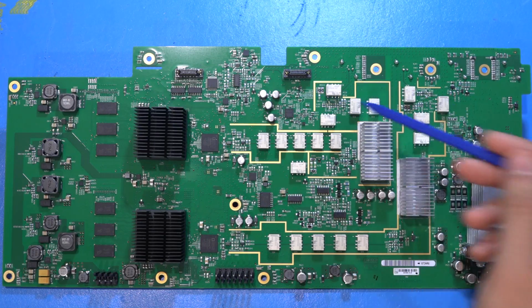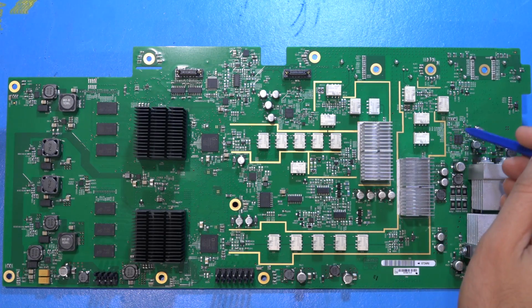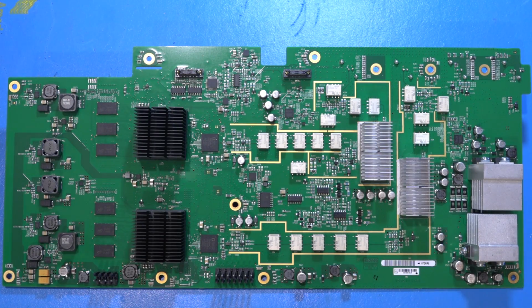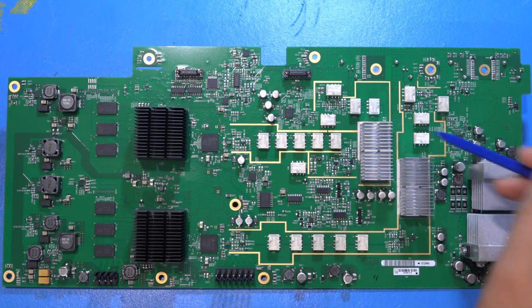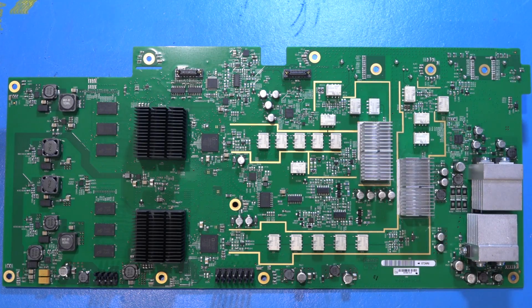Every oscilloscope has, of course, a front-end analog section, and this may be that front end for this instrument. Now, it may not be, but given that there are two of them fairly close to the output, it is possible that at least it is in some way involved in the InstaView circuit. These are not analog to digital converters. Those are on the other side of the board. They're most likely just analog conditioning devices.